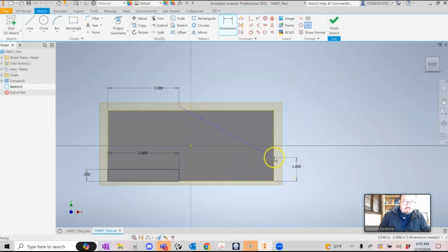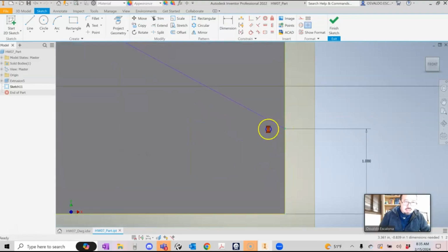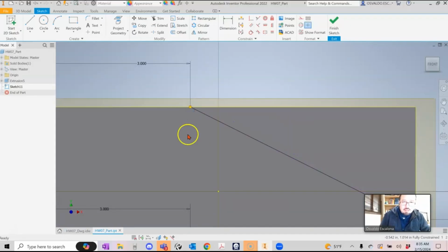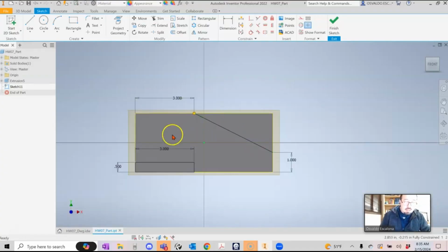And again, if it doesn't snap after you project it, just continue till it snaps, and it has to be black. So if it doesn't snap, let's see, did it snap or not? So it needs to snap. Try to find it and drag it. And if it drags and it doesn't move, it's good. It seems to me like that one's good, but this one is not. I'm gonna grab it till it snaps. It needs to continue. It has to be black, otherwise it's not completely locked.